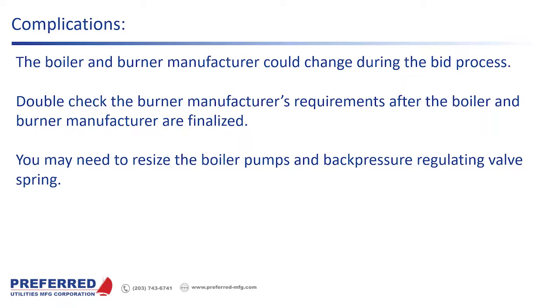And that's happened to me many times, where we didn't catch it until our pump set's out in the field and we find out that there's an onboard pump on the burner, and we need more flow out of the pumps. Like I said before, I size transfer pumps pretty generously. So sometimes we just ate into our safety factor. And I remember one occasion where they said, we're never going to run all the boilers at high fire anyway, so these pumps are fine.